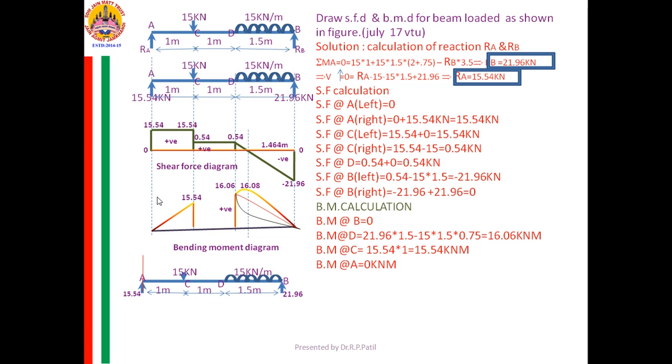Now you are joining those two tips, that is A and C. Before joining you are seeing the shear force diagram. How is the shear force? That line is a parallel line. Therefore, in the BM it is one order higher, that is an inclined line, and we are getting an inclined line. Only we need to confirm that it is not a parabola or anything else.